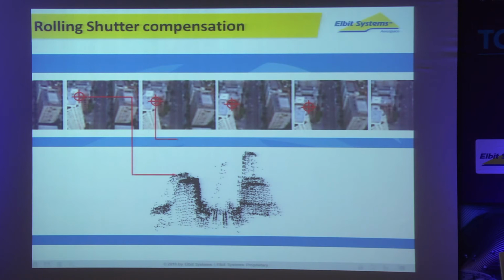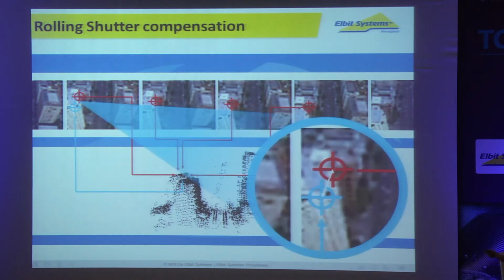So what we do to solve this problem is as follows. We follow the first steps of tracking points and then creating a point cloud by triangulation. And then we project back each point from the point cloud to its original image. And as we can see, they land at a different location from where they originated. And this is because when we do our mesh creation, we use several images, so we do have an effect of canceling out some of the noise, but not quite all of it.